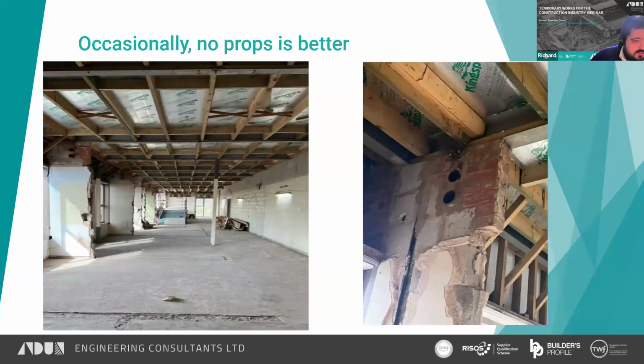And then if you move on, Josh, sometimes simple is better, but sometimes no props at all is better. So this was the fantastic early engagement we were talking about earlier. Instead of propping all these roof beams that you can see here, what we did is we kept in stubs of the walls at the end to still support these roof beams.